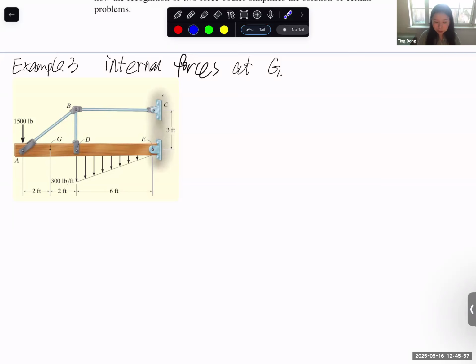We have three unknowns here. We have the reaction force. Of course, this is a two-force member, so it's the force, the line of action either this way or this way. So this is one unknown. Here we have two unknowns, X and Y, right? So of course you can solve for all three reaction forces, but it's just a waste of your time, especially in the exam, especially if you are solving a very complicated project in your senior class. A lot of times, only focus on the information that you need to have. And for example, this is really unnecessary to solve the reaction force here.